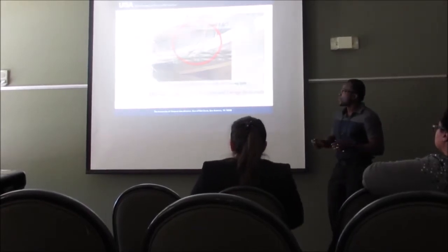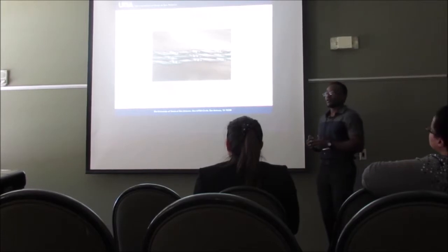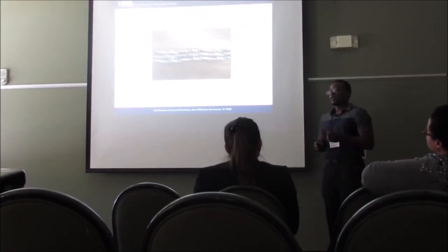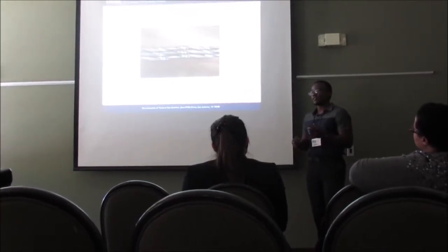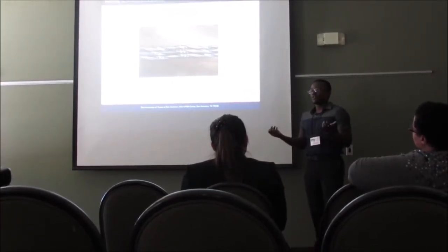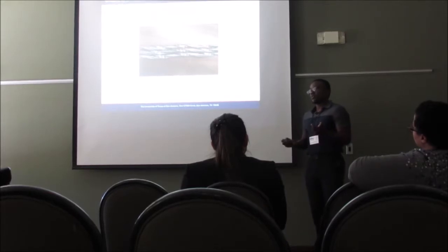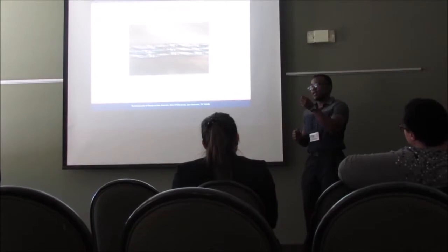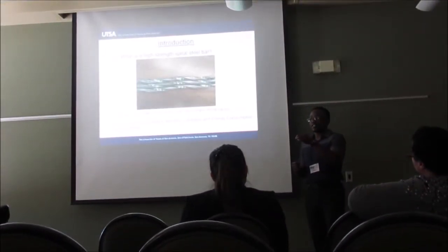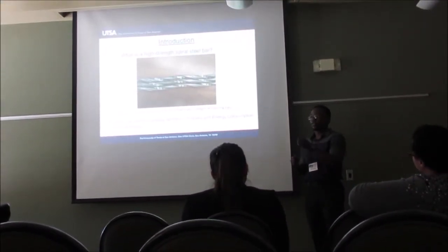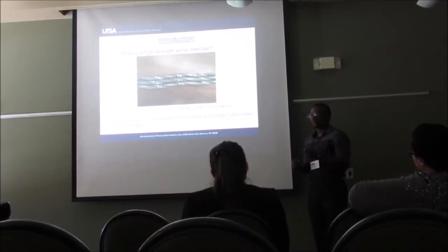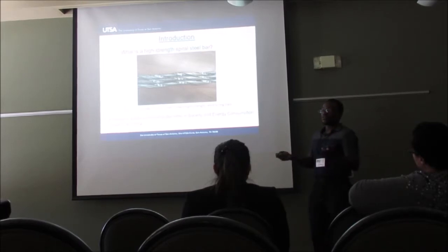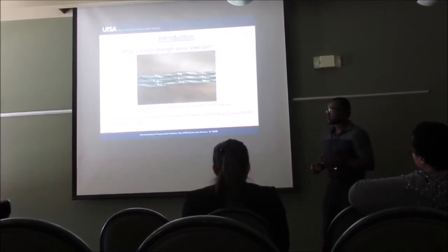And so, with that, what is a high-strength spiral steel bar? A high-strength spiral steel bar, by definition, is a bar that has a yield strength of 72 KSI. By 72 KSI, I mean 72 kilopounds per square inch. So if I have a steel bar and I pull on it, and the cross-section of that bar is 1 inch square, in order for me to create any permanent deformation, I would need to pull on that bar with a force of 72,000 pounds. That's a lot of force, and that's why we use steel bar in reinforced concrete construction.